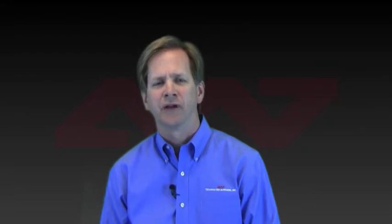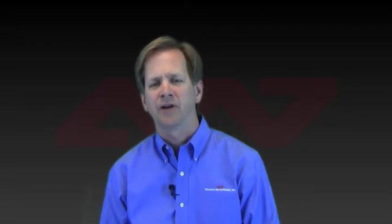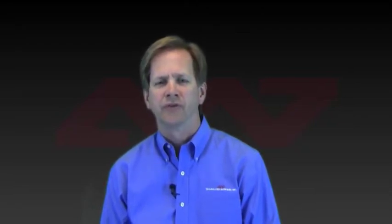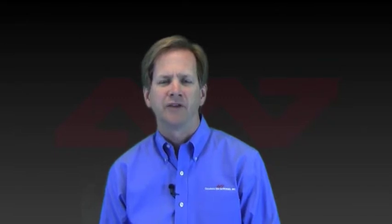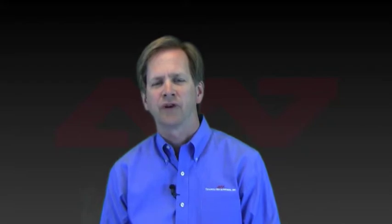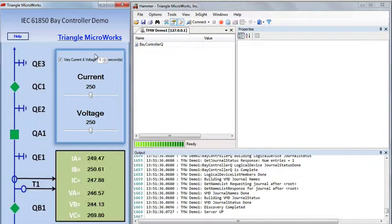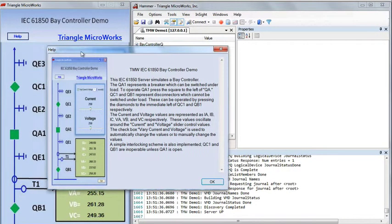For this demo, we'll be using the 61850 demo server as a real-world device. The 61850 demo server was written using our .NET components, and it simulates a Bay controller with a recloser and some interlocks. The ICD file and the algorithm for this Bay controller were provided to us by Christoph Brunner of IT for Power. So here we see the 61850 demo controller running. If we click the Help button, we get a pop-up dialog that explains the algorithm and the interlocks that are used by the Bay controller.